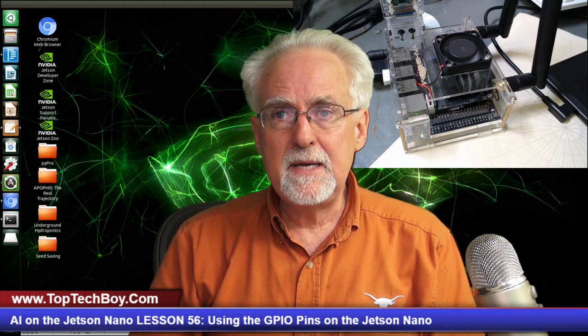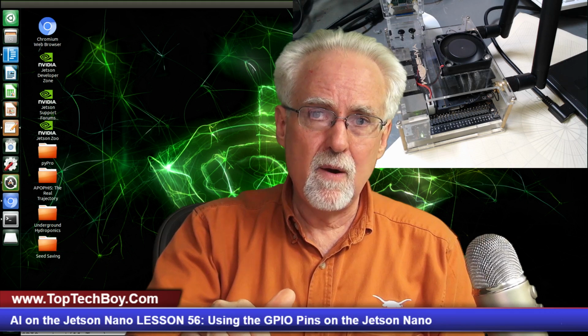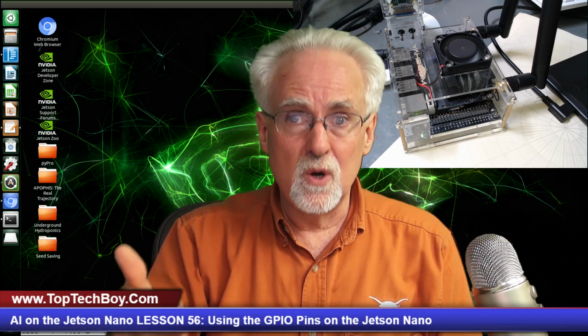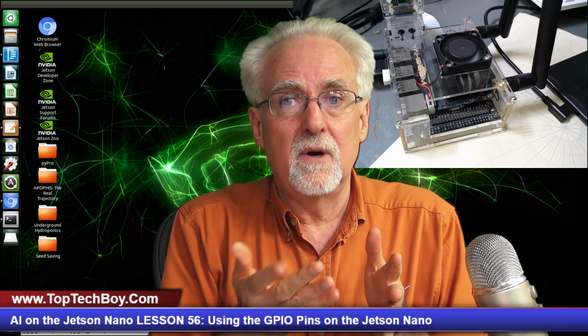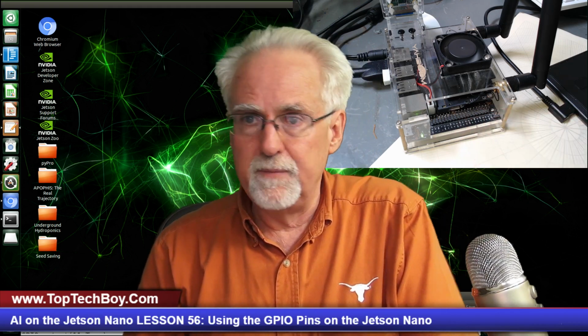So what that means is that with the Jetson Nano, you've got to start thinking about things differently. You're not providing power to turn something on or off, or you're not powering things from the Jetson Nano. You're sending control signals. You've got to think of it in terms of control signals. You're sending a signal that you want the LED to turn on, or a signal that you want the LED to turn off. You're not powering the LED itself from these GPIO pins.